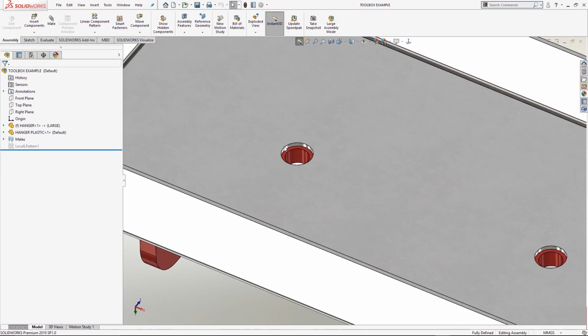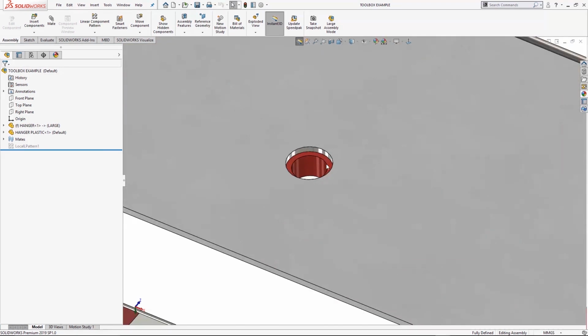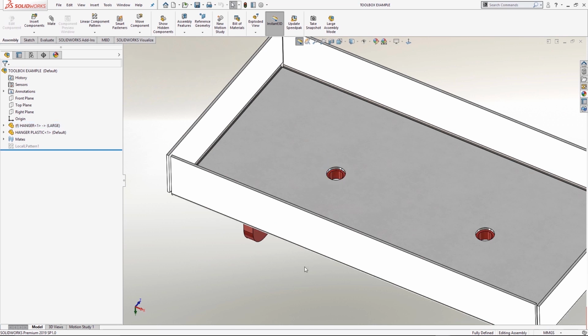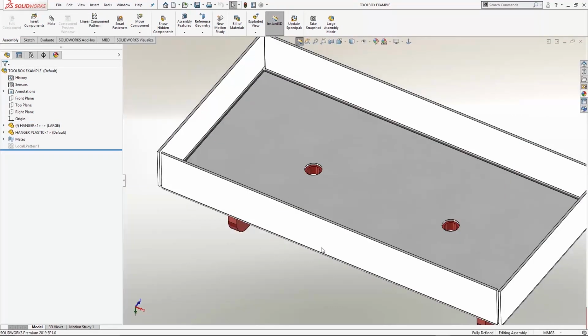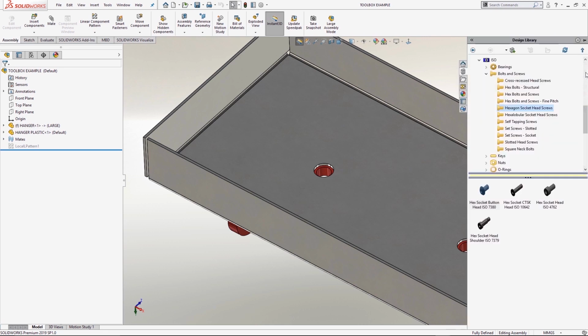Now PEM is like a self-clinch nut or a riv bush or whatever you want to call it, and all I've done in my SOLIDWORKS model is this hole here. I've used the hole wizard to actually use the PEM standard. So within our hole wizard we can actually specify that I want a M6 PEM self-clinch nut to go in there, for example, and that means that I don't have to pick up the reference from my specification book. So let's begin. I'm just going to open up my design library.